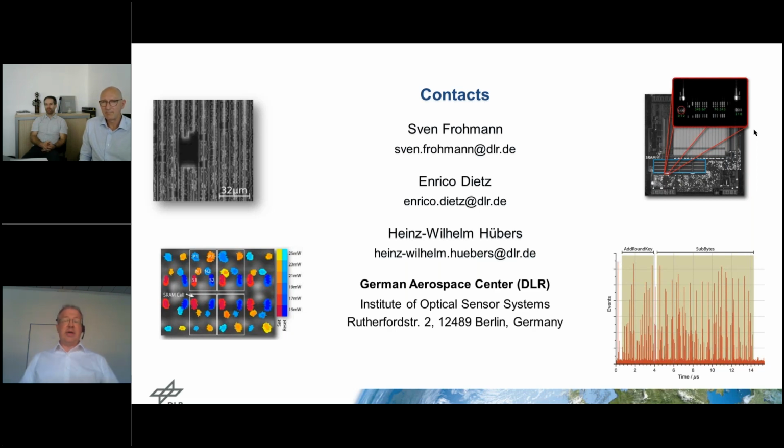It's already required. If a company sells devices like security ICs, they have to show that they are robust against well-known side channel attacks. They also have to prove it. The thing is, when we can alter an operation or a transistor by light, it means in general these integrated circuits are sensitive to light. So you also have to make sure that someone using a flashlight cannot somehow alter the logic or the operation. These ICs have to be tested, and they have to show that they are robust against certain well-known attacks.